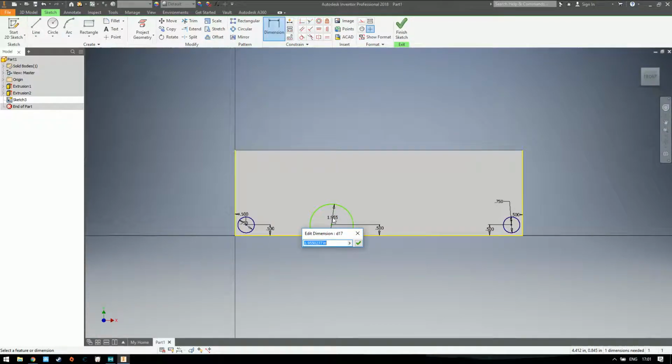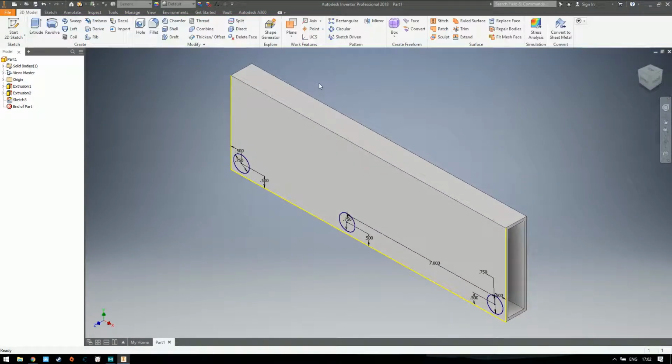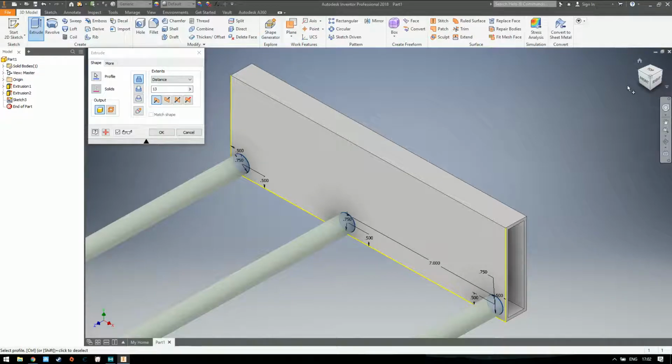As you can see, I'm slowly turning every green part to become a solid blue. Because we still need to offset the center to this, let's just offset by 7. Whatever, I'm just making up some measurement. Then click OK. Then extrude. If you want to extrude multiple things, press Shift, then left click on every single closed area you want to do.